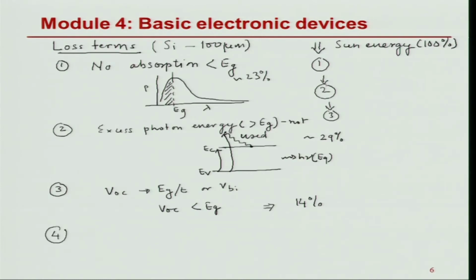I have the next loss, which is coming basically from the fill factor loss, because this fourth loss is there, because when we made our ideal device we would have liked it to be this way, but we know that J comes in this manner, and that is because there is a fill factor. So, it is not the JSC times VOC that we get, we get a less value. So, if I take certain values from that, I will lose an additional 5% from here.